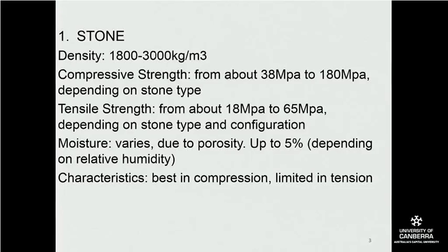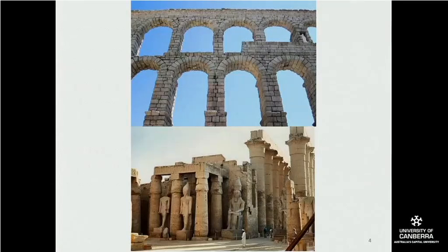The moisture varies depending on relative humidity and also the porosity of the stone, and can be up to 5% or more, depending on whether it's exposed to water or not. And the characteristics are similar to concrete in that it's best in compression, in fact very good in compression, but quite limited in tension. Of course, in terms of concrete, we do have steel reinforcing to make concrete work better in tension.